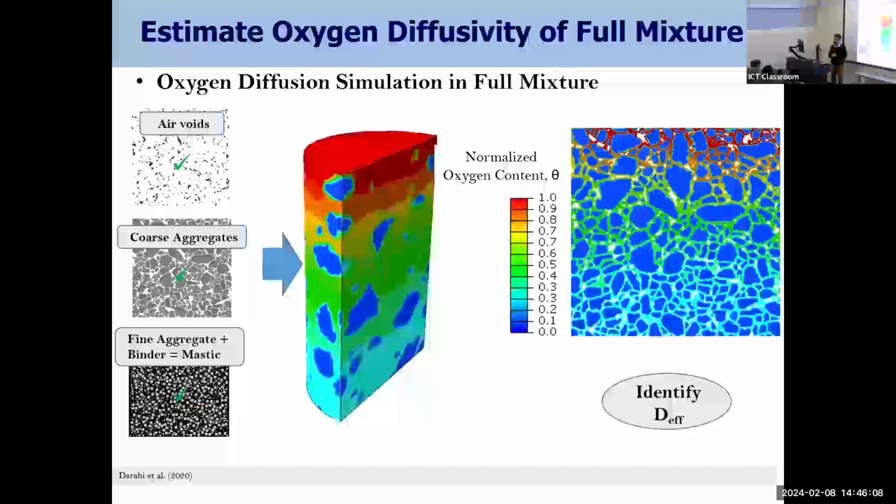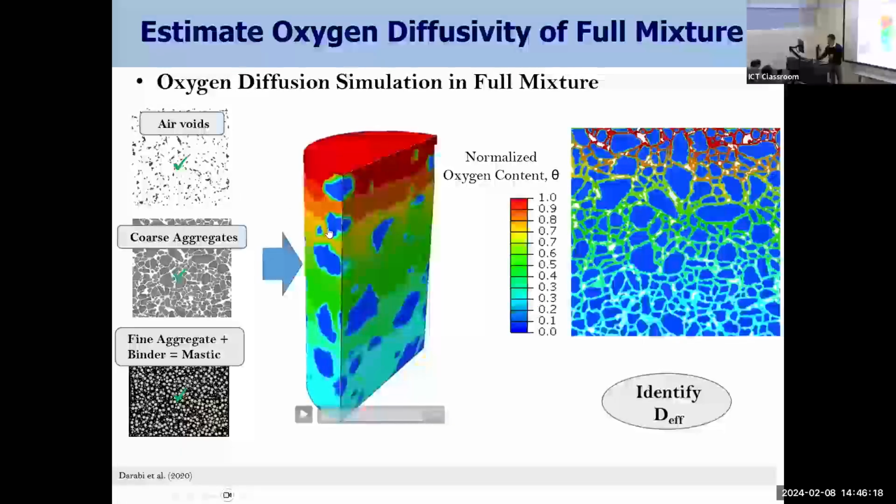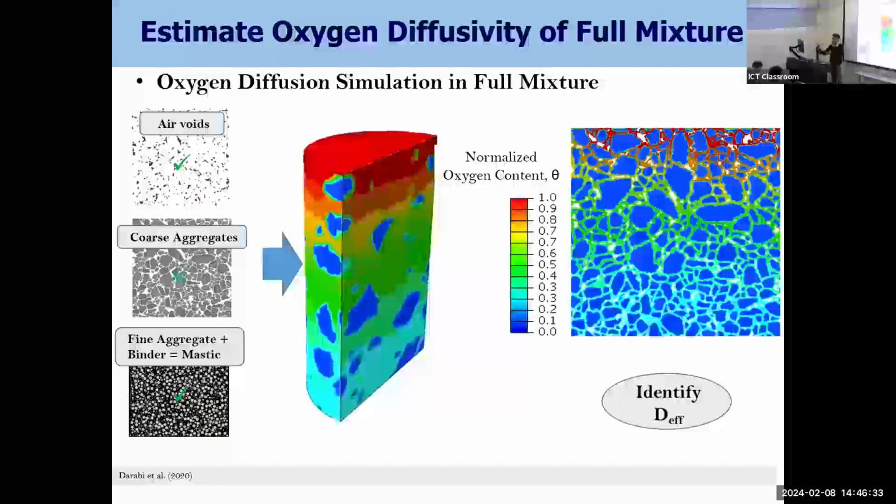I see. So now with this model, did you go to how it affects the binder in the profile? How it physically affects the properties of the asphalt concrete? So we have a model that couples oxidative aging with viscoelasticity and a damage model.